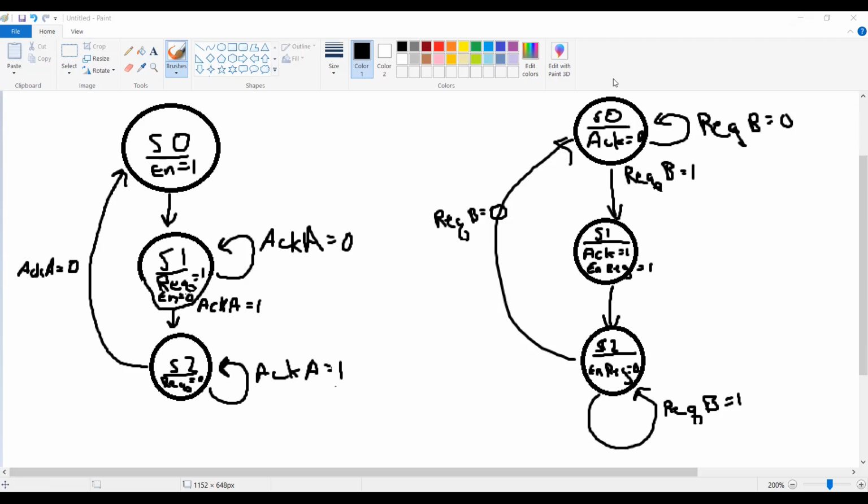acknowledge as input, enable 1 as output, enable 2 as another output, request as input. You don't connect them with signals at the moment. When you are sure about each one, you can move to removing the input and output from the entity and start adding signals.